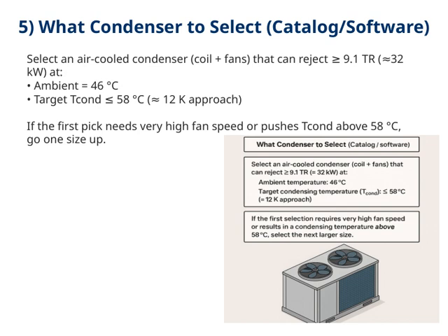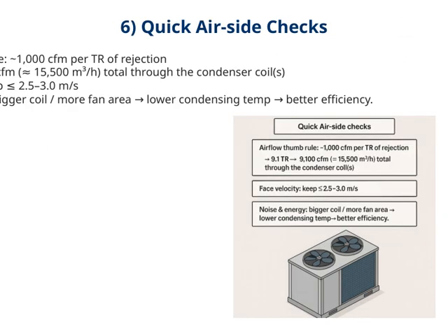Going one size up can help reduce the fan load and keep the temperature within the optimal range. Remember, selecting the right condenser isn't just about meeting capacity. It's about ensuring reliable performance under the worst-case conditions we might encounter in operation. Let's take a look at some quick airside checks that can really make a difference in system performance.